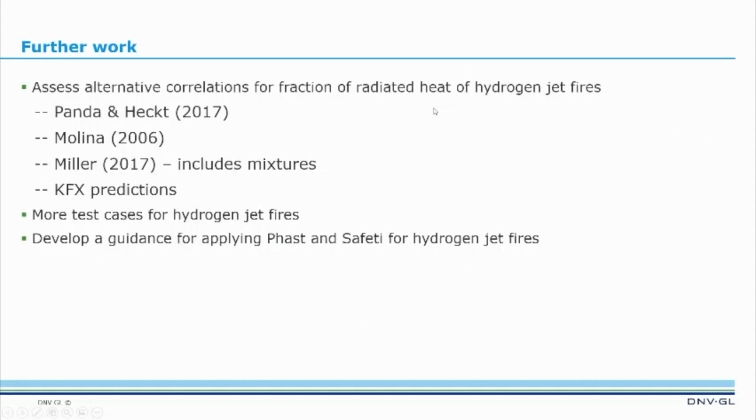So just moving on, this is work we're doing. We're assessing the applicability of these different models and correlations and looking at different options to enhance Phast. We're also using KFX and validating KFX, but also looking to see if we can use KFX to investigate some of these behaviors, particularly understand the behavior that Derek Miller's identified, and also improve our guidance for applying Phast and Safeti for hydrogen jet fires.